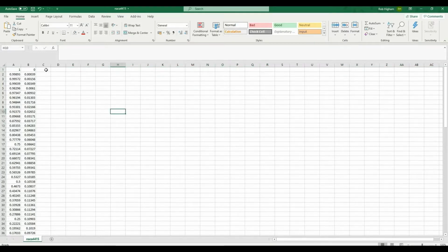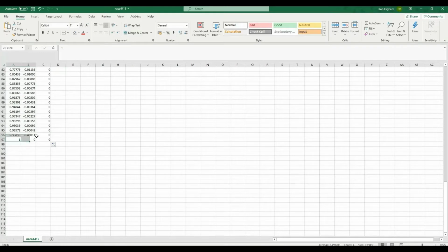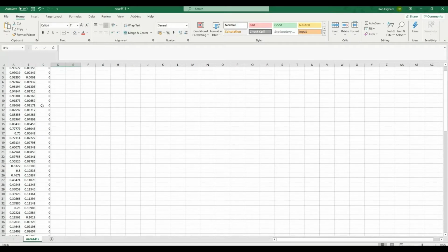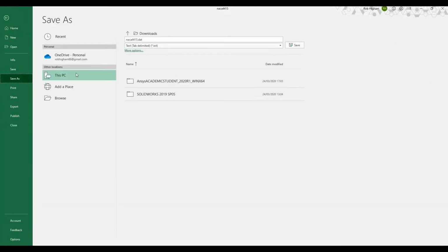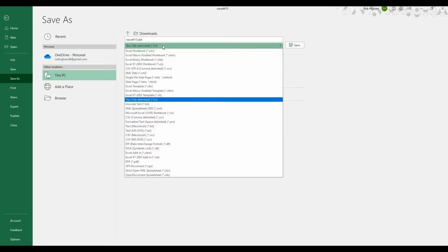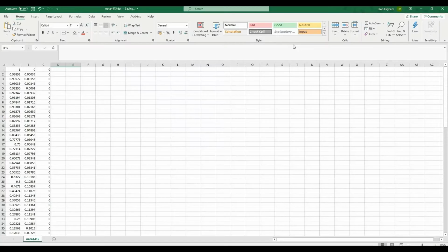Great. So, couple of points. We need to make sure that only the data is saved, so we delete that top line. And then what we can actually see is X data in column A, Y in B. Now actually we need to make sure we add Z. For us we're going to import this in 2D, so Z is always 0. And then we look at the bottom and we make sure the profile is closed, and we do that by making sure that the end is the same as the beginning. So now we can save this file. And again, it's important to save it as a DAT file as highlighted on the screen. So with that now saved, we are ready to import into Solidworks.